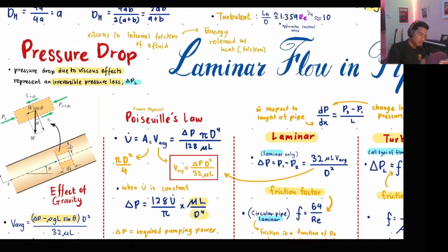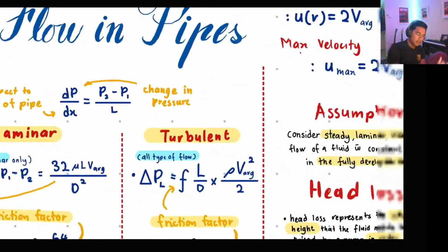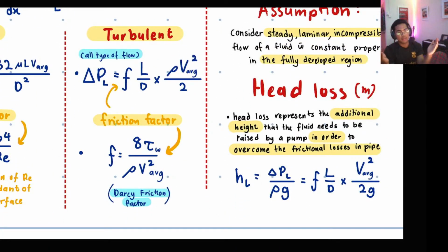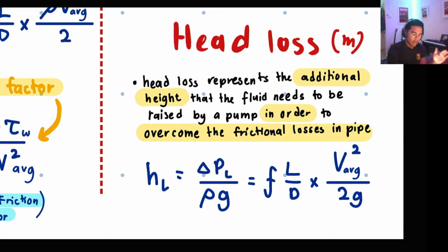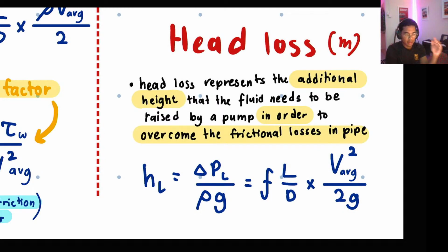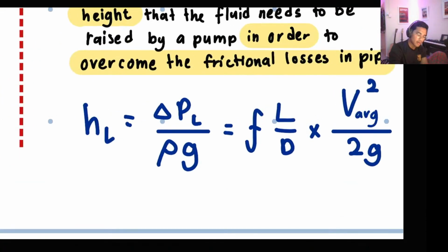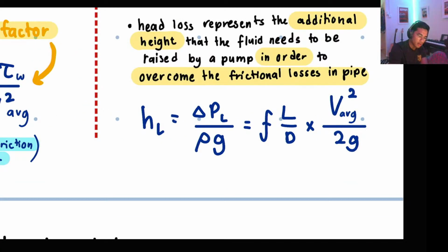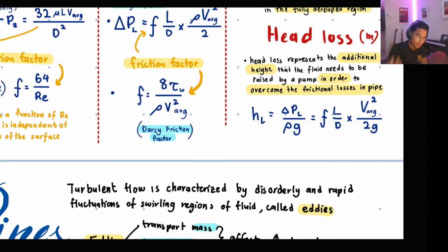If we talk about pressure drop, people would say the pressure drop for that system is 30 kilopascal, so you don't know how much pressure drop it actually is, because you don't know the dimension of the system. So head loss is used because it is much simpler than pressure. It already includes the density and also gravity, so it's a simplified pressure drop.